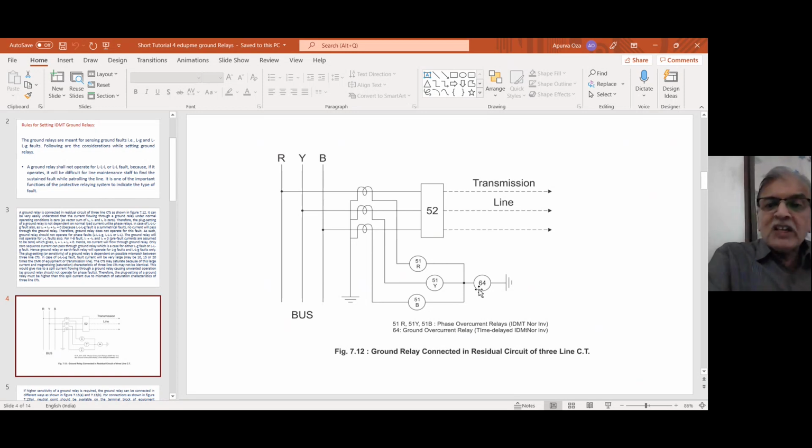Right. Then what is the consideration? The consideration is possible mismatch between the 3 line CTs. When triple line fault occurs, say for example, these are 100 by 1 CTs, triple line fault is 1000 ampere, then 100 has to be reproduced as 1, 1000 must be reproduced as 10, but unfortunately 1000 is not reproduced as 10 because CTs saturate.